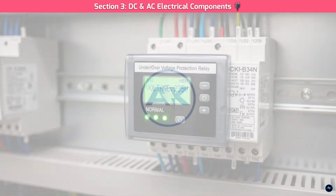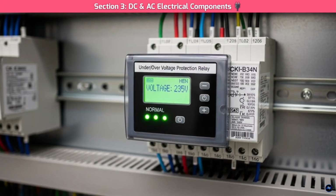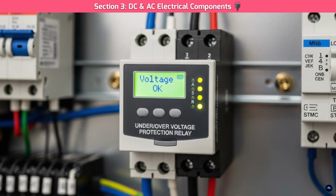Component 4. Under-over voltage protection relay. Now for one of the smartest parts of the ACDB, the under-over voltage protection relay. This little device constantly monitors the grid voltage. If the voltage gets too high or too low, the relay automatically disconnects the inverter. This is a crucial safety feature that protects your equipment and prevents a dangerous condition known as islanding, where the solar system keeps powering a section of the grid even when the utility is down.